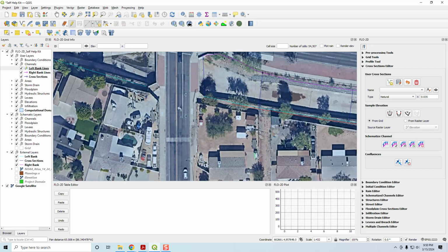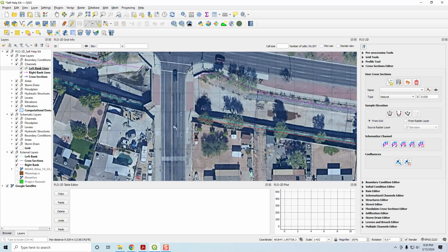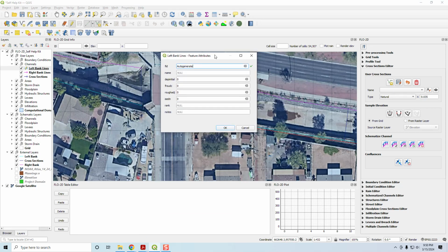So now I'm going to put this here, but let's check the grid. Okay, so do I want that to be here or do I want it to be here? It kind of doesn't really matter, so we'll just do it here. And then I'll right click, and this needs limiting Froude, for, remember in the RAS we used 0.9, so we'll do that again because this is an urban channel.